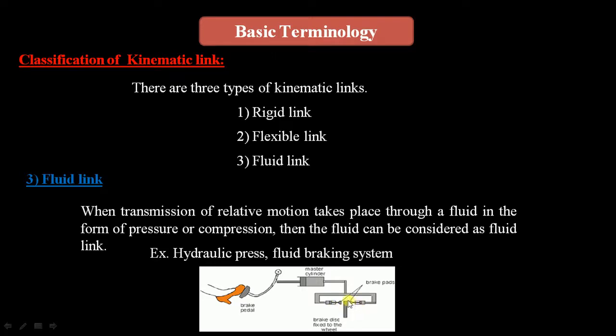Then the brake pads will move forward, come in contact with the disc, and apply the brake to the disc. Likewise, the motion transmission is taking place through the fluid here. So in this case we can consider the fluid also as a kinematic link.